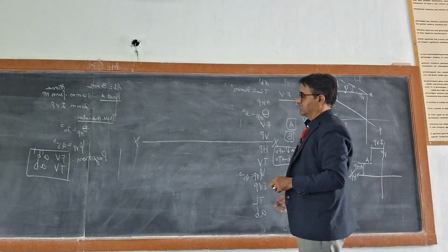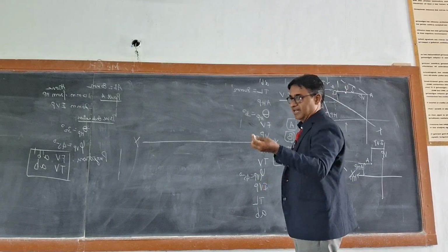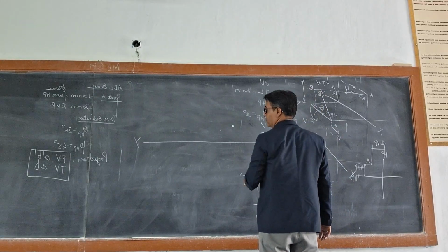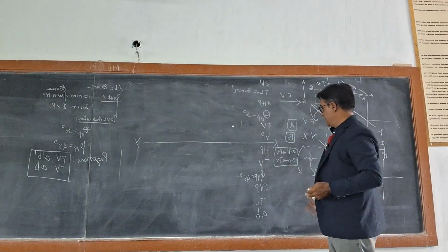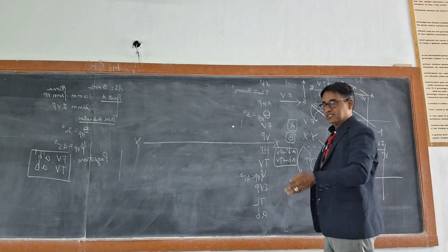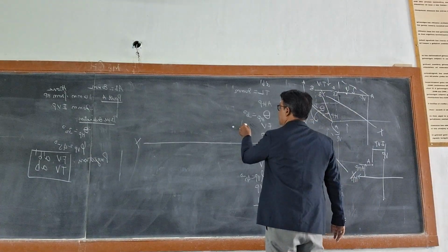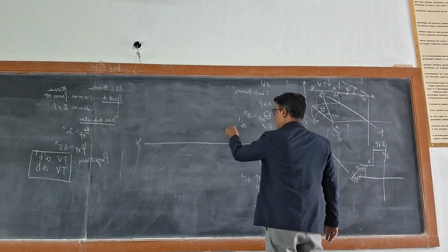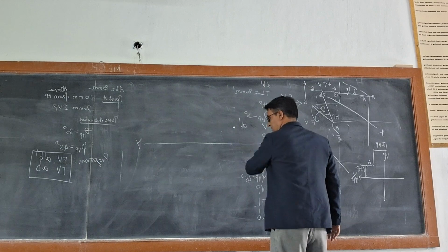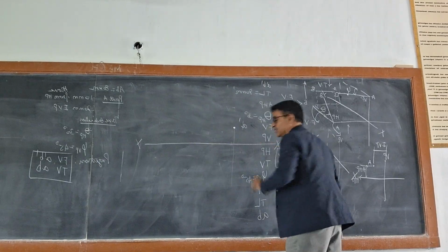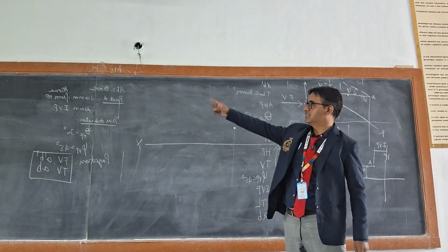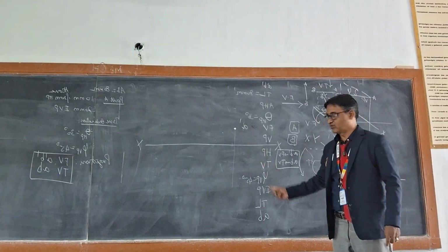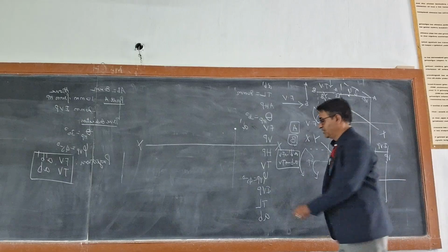So I am going to first understand that. Above HP distance is 10 mm. Therefore, above HP is 10 mm. And the logic here is A and A dash will be in line with each other. Meaning this is my front view. Therefore, it is represented by A dash. Now it is in line. Therefore, draw a line perpendicular to XY. Okay, now what is in front of VP distance? It is 20 mm, because in front of VP comes under XY, below XY. Therefore, in front of VP is 20.